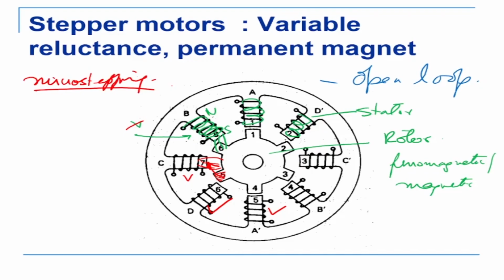Now what is micro-stepping? It essentially means that, what we were doing is we were applying one voltage to one of these coils. We are applying a voltage here. Now suppose I activate both the coils, V1 here, V2 there. So what will happen, it will be attracted by this one and it will also be attracted by this one. Okay, now where will it go?